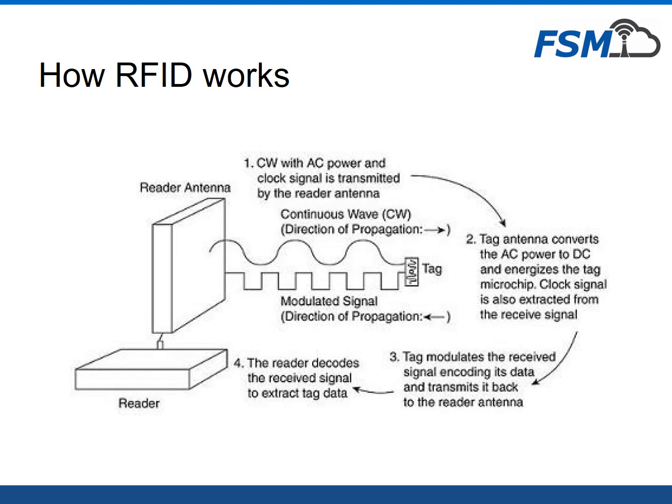which the reader, depending on the power it's configured for, sees as digitized information riding on the back of the modulated waves. Therefore, it takes these modulated waves, demodulates them, separates the carrier wave from the digitized signal, filters the digital signal, bit checks it, and then pushes it back into the network.